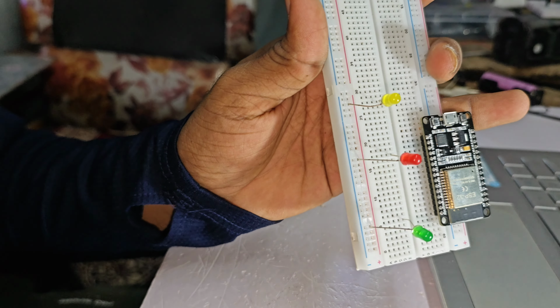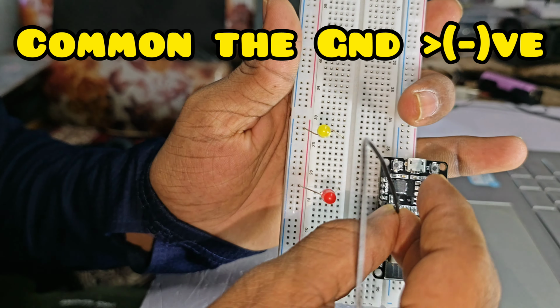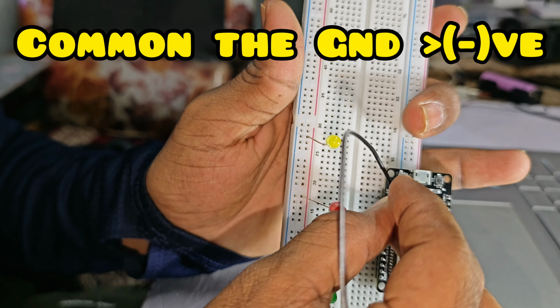Now I will take the ground from the ESP32 and make all three common, so all of these three are ground. Now, which pin is LED 1 connected to? Let us see. LED 1 is 2, so I am connecting it to 2.